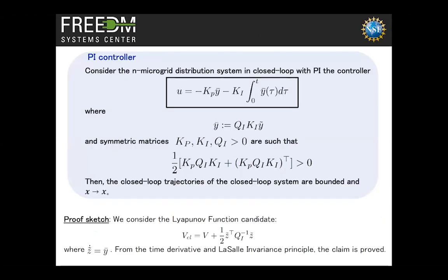By making use of these specific physical properties such as incremental passivity and designing in DQ space, which makes the design linear, we came up with this still linear-looking multivariable PI controller. And again, I would like to reiterate the message that what is allowing us to have a linear controller despite my plant being nonlinear are these two properties. One is the DQ projection, which allows me to do the design in the linear space, but still guarantee stability for the nonlinear system. But despite the threat of losing controllability, I have passivity to save me in my final Lyapunov proof.